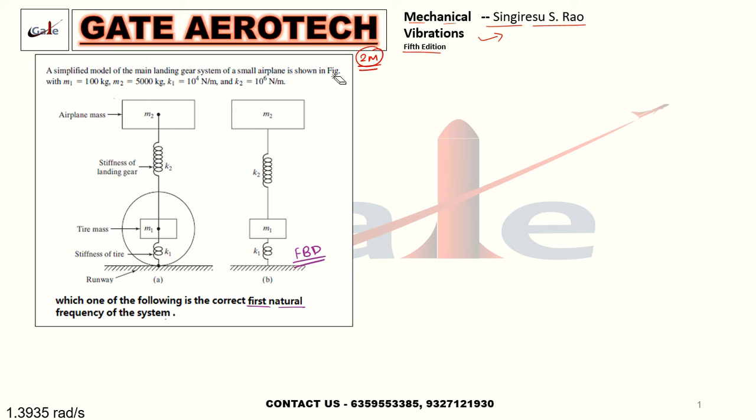Shall we start? Yes. Now if you have this kind of question in the exam, where M2 and M1 are given, K1 and K2 are given, and they are asking simply to find the natural frequency, one of the best methods you will encounter is the matrix method. I hope you have seen this kind of matrix for solving a 2 degree of freedom system.